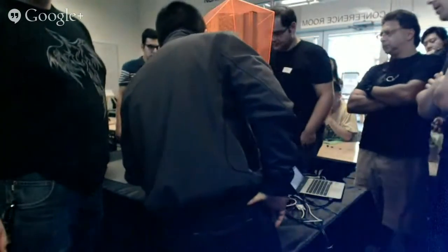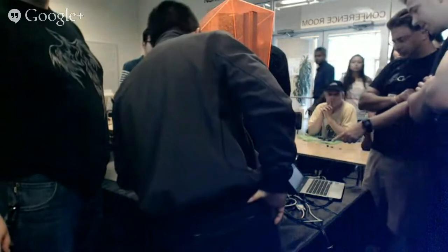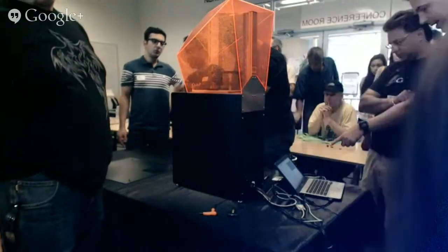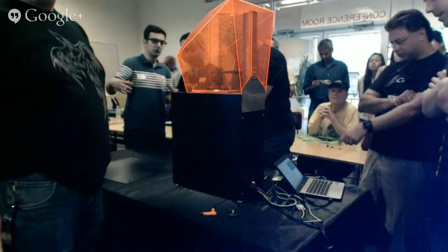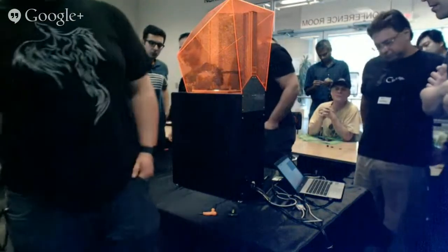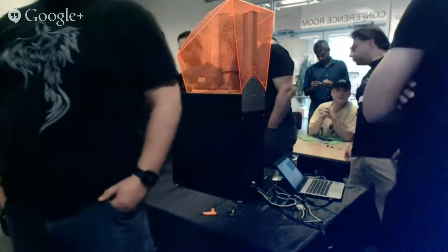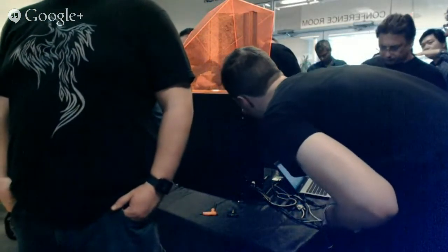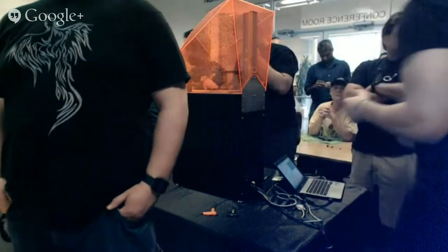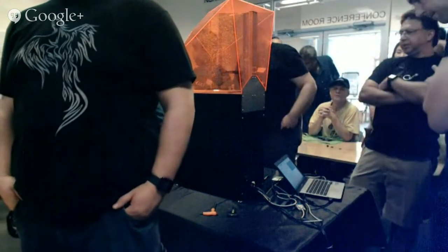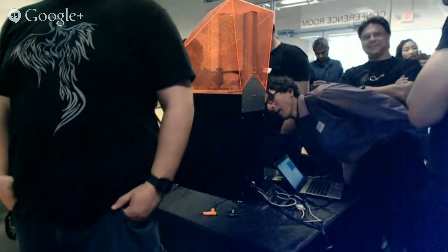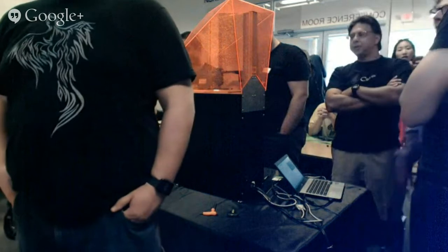After printing, do you have to wash the part? You try to avoid using alcohol as much as possible. These vats are made from acrylic. Acrylic and alcohol don't get along. Now this is high quality cast acrylic, so it can withstand alcohol. It won't crack. If you use pressed acrylic, like really cheap acrylic sheets from Home Depot, those you can't let touch alcohol, otherwise they'll craze right away.